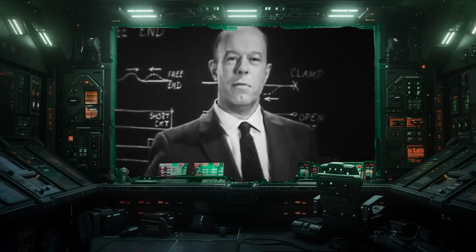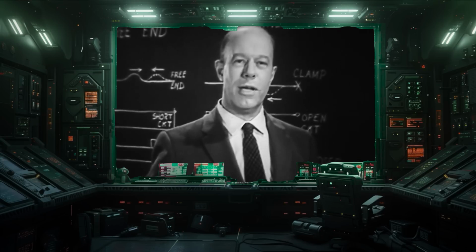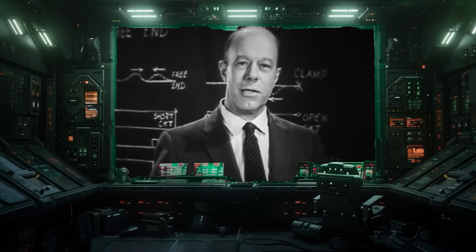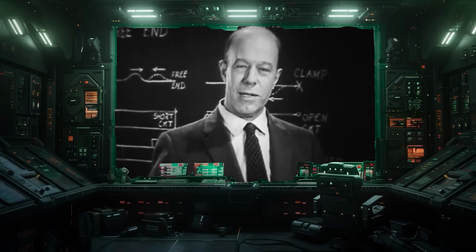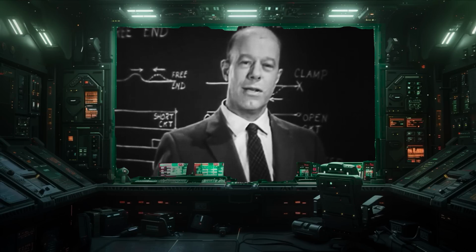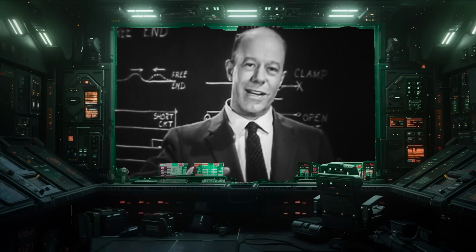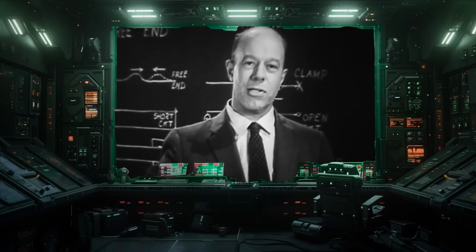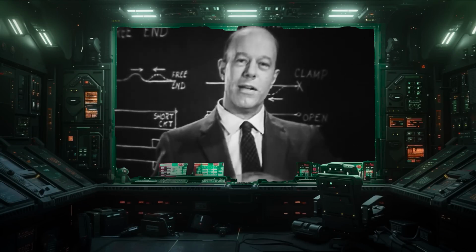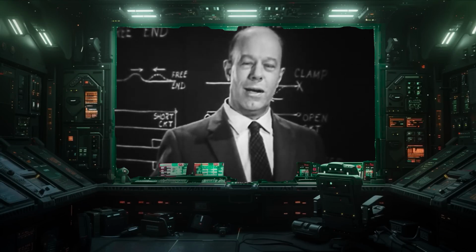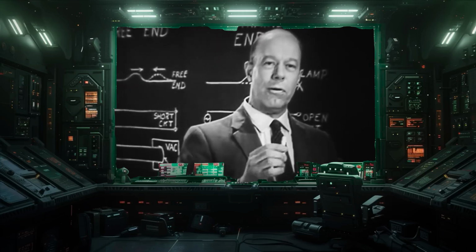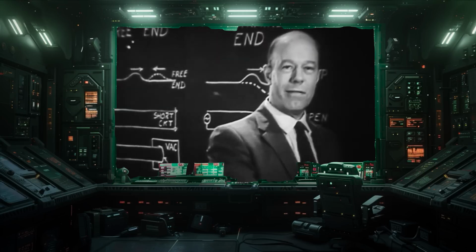You're probably most familiar with the term impedance through your studies in the field of electricity. But this impedance concept is just as applicable to wave systems of other kinds as well. On our mechanical wave machine there, for instance, the cause of the waves is the oscillating torque which I apply to the first cross arm, and the result is the oscillating angular velocity imparted to the medium. On that structure, then, the mechanical impedance is the ratio of the applied torque to the resulting angular velocity.